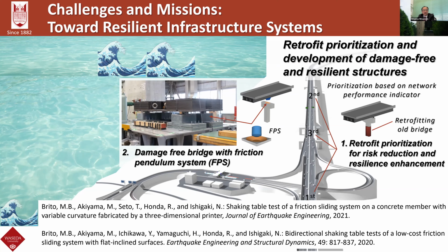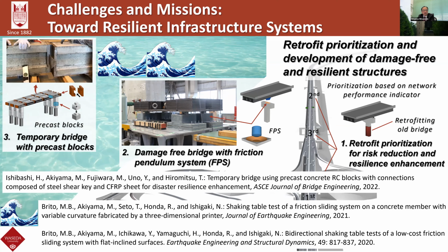However, for giant tsunami, many bridges, even retrofitted bridges, were washed away, as observed during the field investigation after the 2011 Great East Japan earthquake. So many bridges would be washed away. So the accelerated bridge construction, ABC concept, should be applied to temporary bridges to save on-site construction time, and help roads reopen immediately after the event.